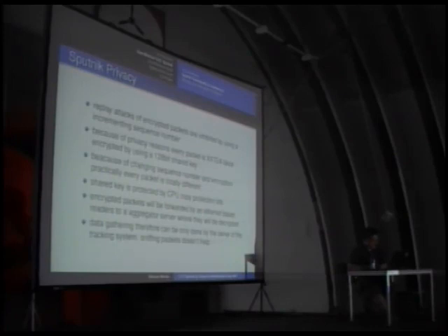Again, the transmission is encrypted by using XXTEA block encryption and a 128-bit shared key. We use an incremental sequence number again to make sure that every packet is different, because if only 1 bit swaps in the packet, because of the block encryption, the whole packet changes completely. The shared key is protected by the usual CPU copy protection bits. This is an average security, so you can't take a simple program and read out the keys used.